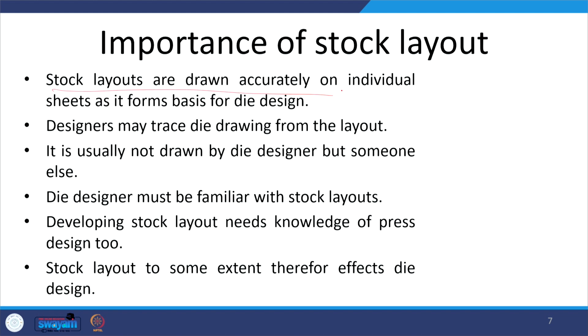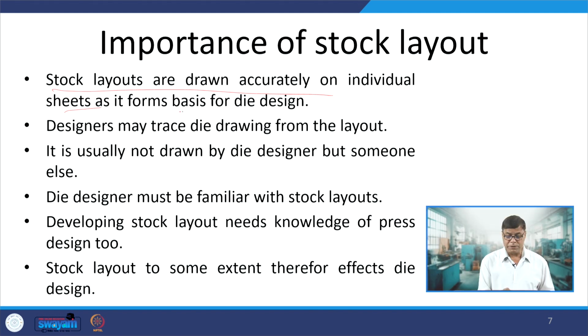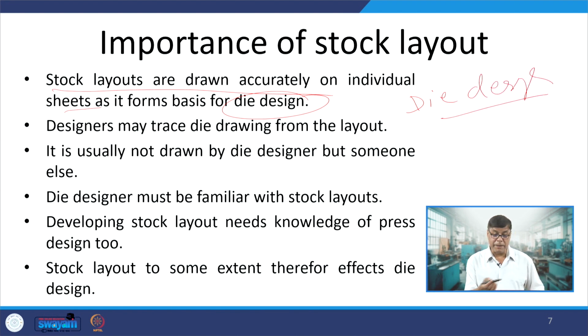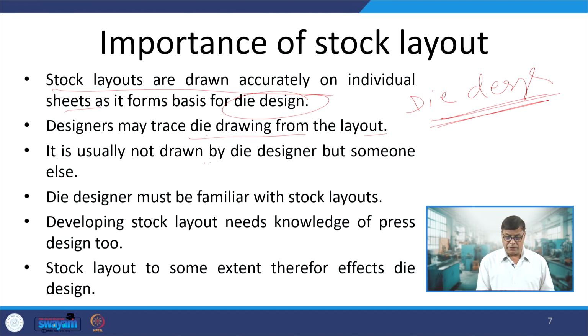Stock layouts are drawn accurately on individual sheets, as it forms the basis for die design. The design of the die is one of the aspects that depend on the stock layout being designed and identified, and designers may trace the die drawing from the layout. This forms the basis for the die design. It is usually not drawn by the die designer, but by someone else, but the designer must be familiar with the stock layouts, what it is and what its importance is.